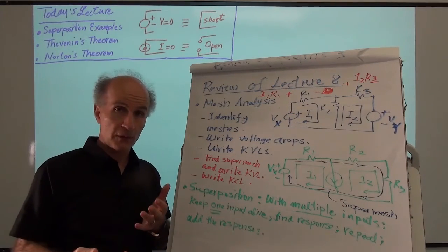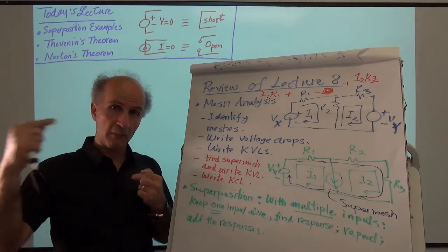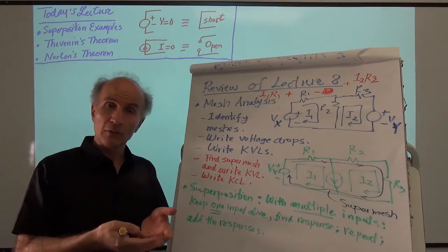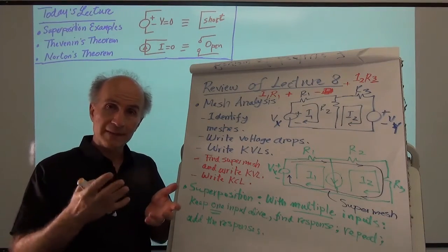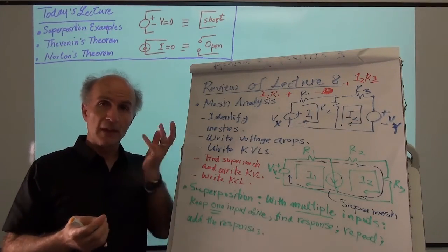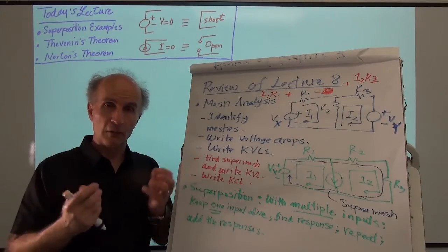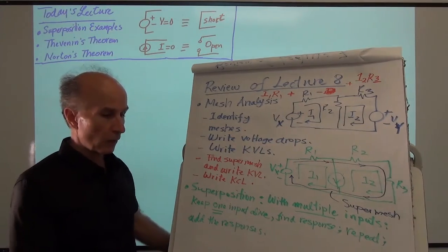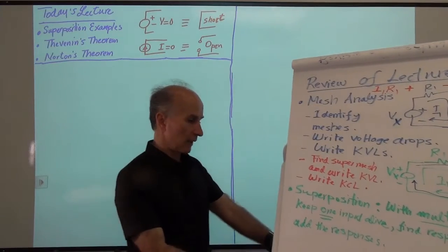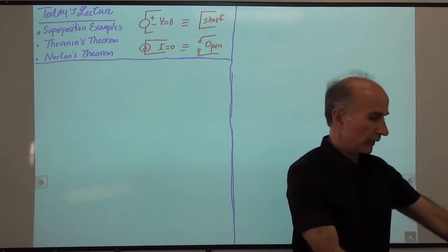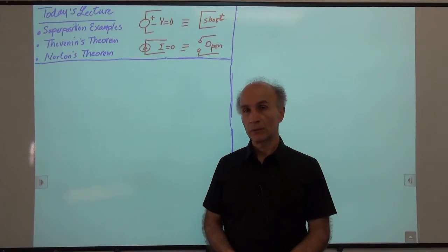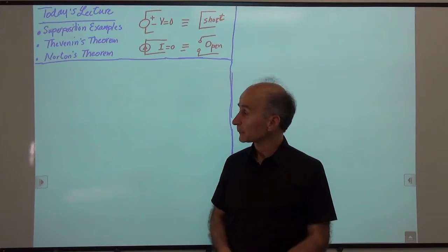So it's natural to assume that if my voice and the music go through the microphone at the same time, the resulting voltage will be equal to the sum of the voltages that we obtain in those individual cases. So today we will go over superposition and its procedure and look at some examples of how we can use this idea to simplify circuits.